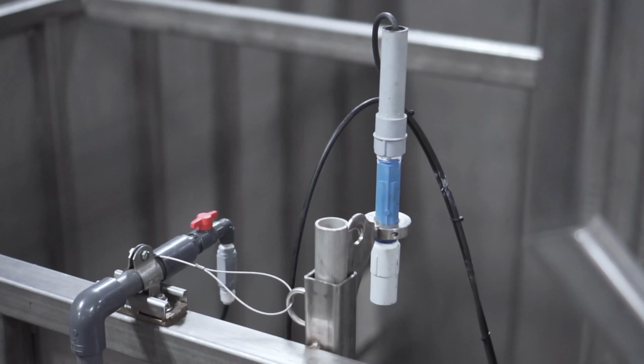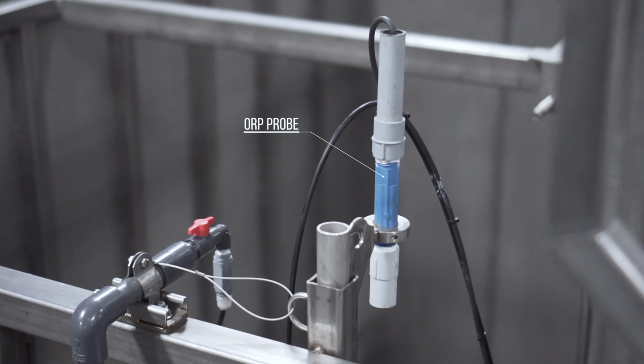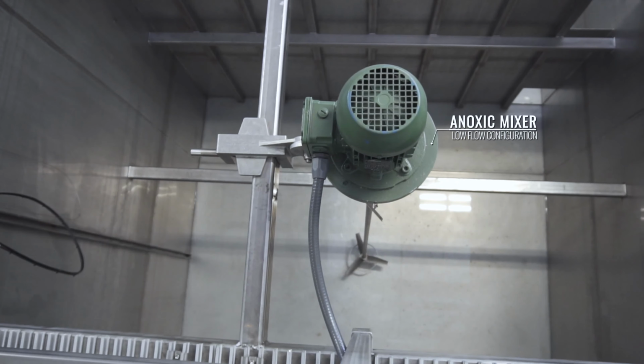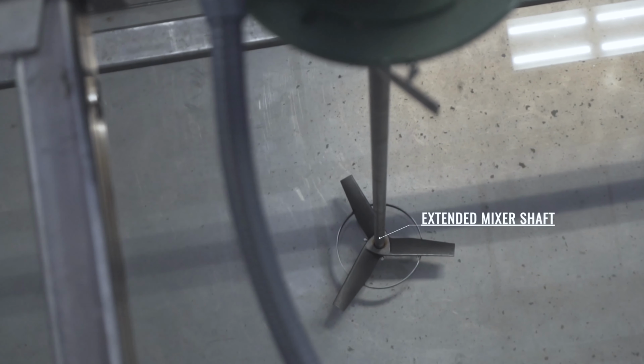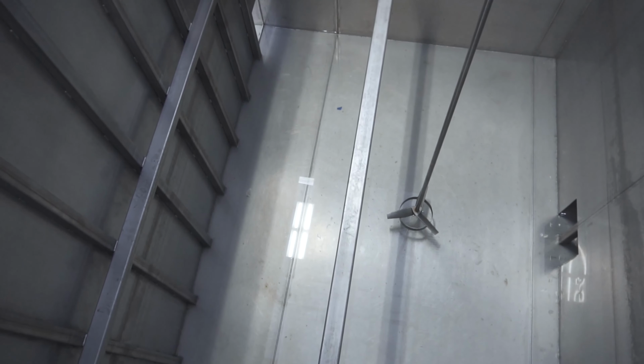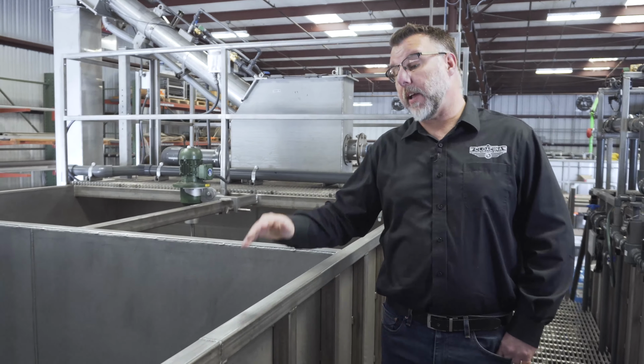We supplied an ORP probe to ensure conditions are right for denitrification. This system is also supplied with a low flow configuration, so we extended the anoxic mixer shafts to ensure the system can operate at lower operating depths. From the anoxic process, activated sludge flows by gravity into the first aeration chamber.